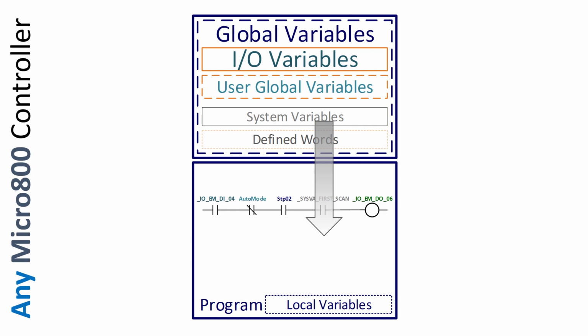And this is a really nice bit to use if you want to tidy up your data table values in a situation where you had a power failure, or you had to go into the program mode to make changes, or you shut the system down. You want to go up in the first scan bit. It's only going to be on, which means this instruction is only going to be true for one program scan, and you can use that to determine whether or not logic gets executed.